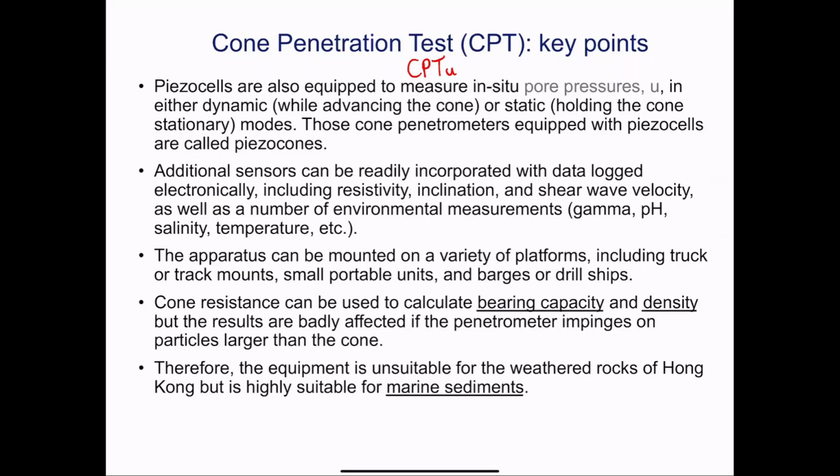The core limitation of CPT is perhaps if you run into very granular material, core stones, boulders, then you're not going to be able to push it through. Then you have to extract, find another location, and penetrate further. This CPT test, as we discussed quite a bit, is quite suitable for marine deposits, for land reclamation, but you won't see this being used for CDG slopes or granular material, or weathered rocks of Hong Kong.